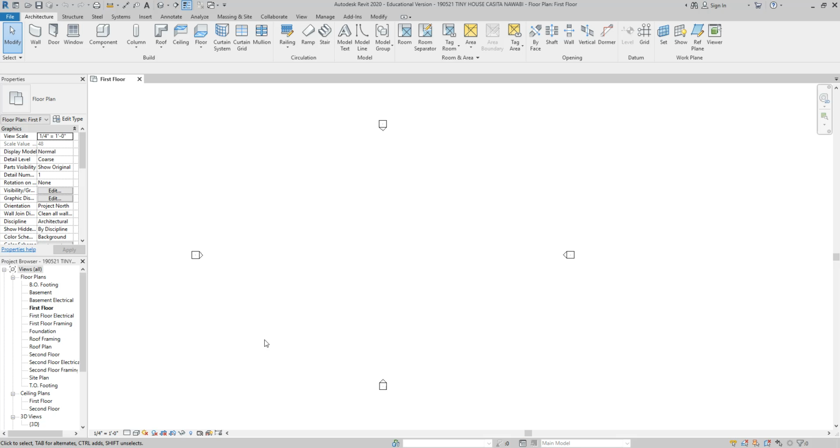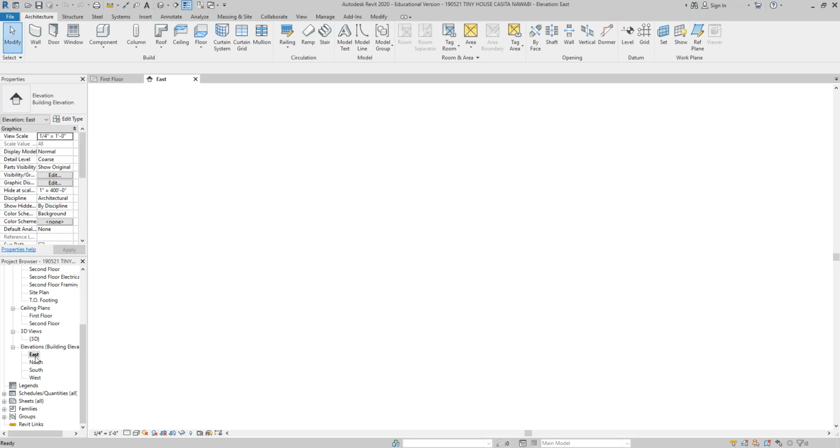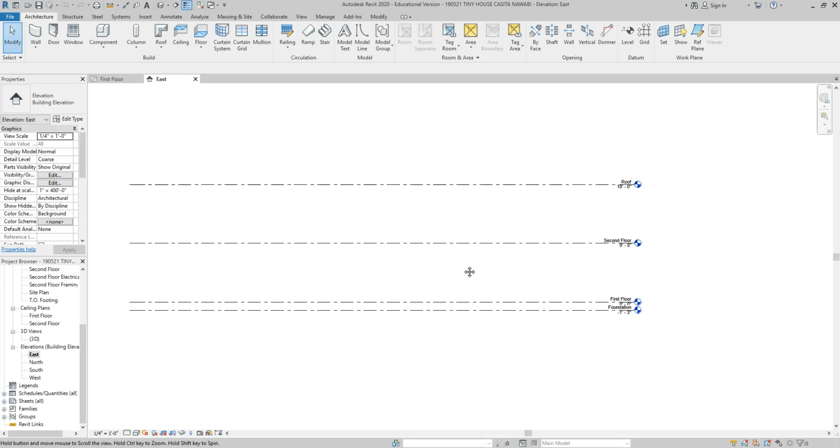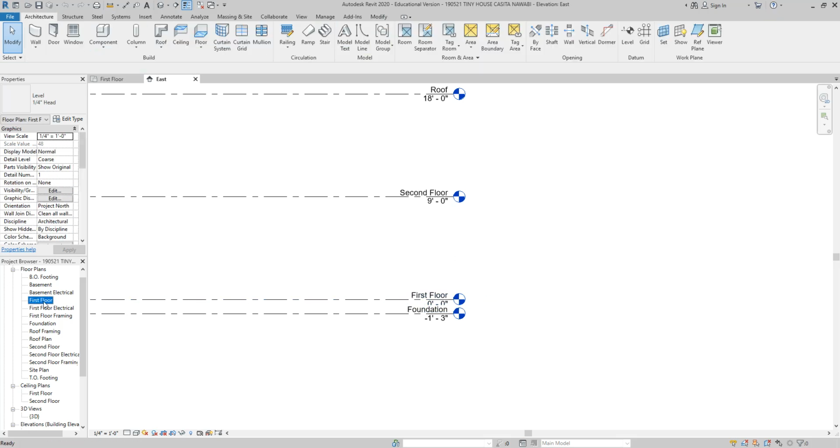Now let's go ahead, we went over wall types and levels. Let's go to our levels and set those up. So what view would we set up our levels in? Elevations, yep. So hop into any of your elevations. And we're going to go ahead and go through some of these. Let's do a quick review while we're here. So first floor here is this same first floor.